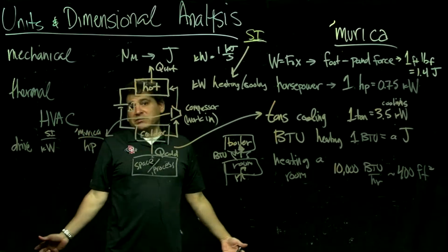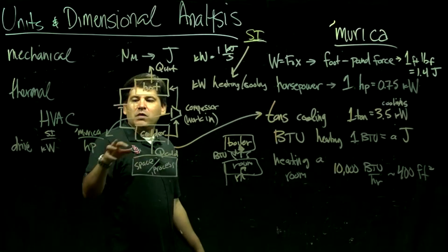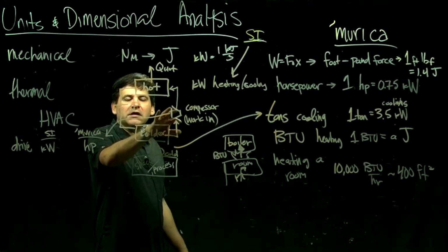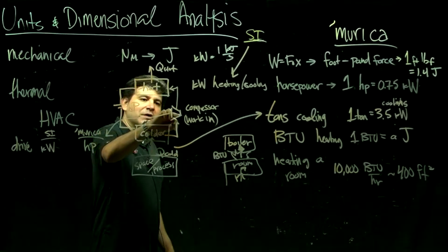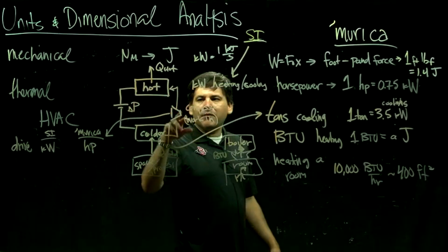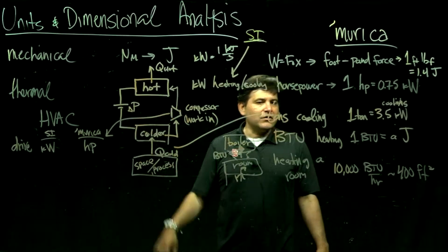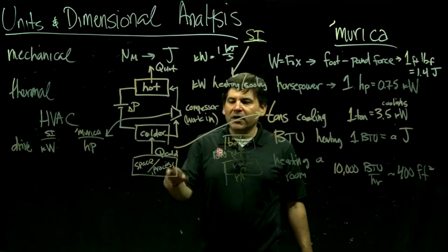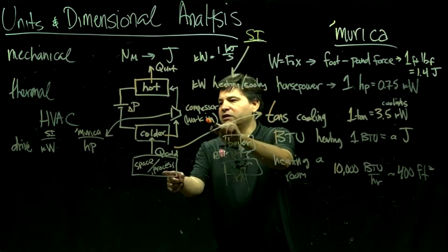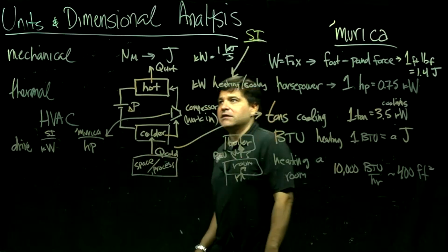So I guess it's more specific. In America, you would say this is an HVAC with a 10 horsepower compressor motor. Because when you're talking about horsepower, you know you're talking about the motor, that's good. But it doesn't tell you about the capacity of its cooling. If you're talking about the capacity of cooling in America, they would use the units of ton. So these both are units of power: horsepower for the motor, tons for capacity.